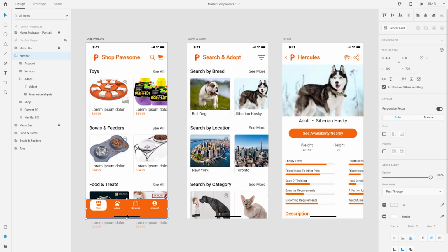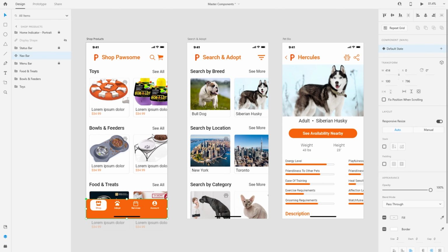So I'm going to right click on this and make it a component, and immediately you see that there's a green border around that particular item, and the top left corner, if you notice, has changed into a diamond with green color. That really indicates that this is the main copy of the component. So any changes you make in the main copy are going to be propagated in all the instances of this particular component wherever you've used it, right?